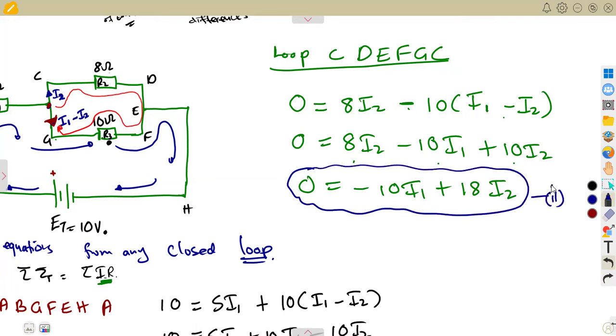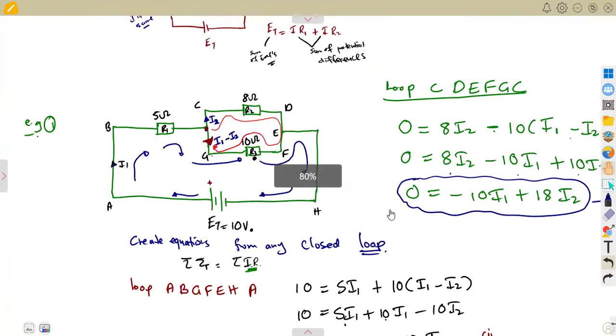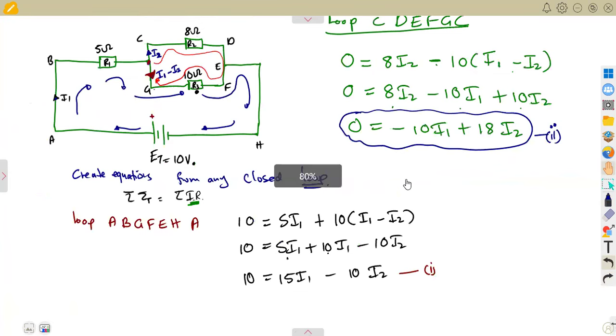So this is enough. Once you have got two equations, you have to solve for I1 and I2. I do not know the way that you are going to take another loop, or whether you're going to consider the loop going the outer way like this, as long as it's a closed loop. Guys, the formulation is in your hands. At the end, these currents are going to be the same. Despite the way that you have taken, whether you used this loop or that other loop, at the end, the values of the currents are supposed to be the same. So this is what you have.